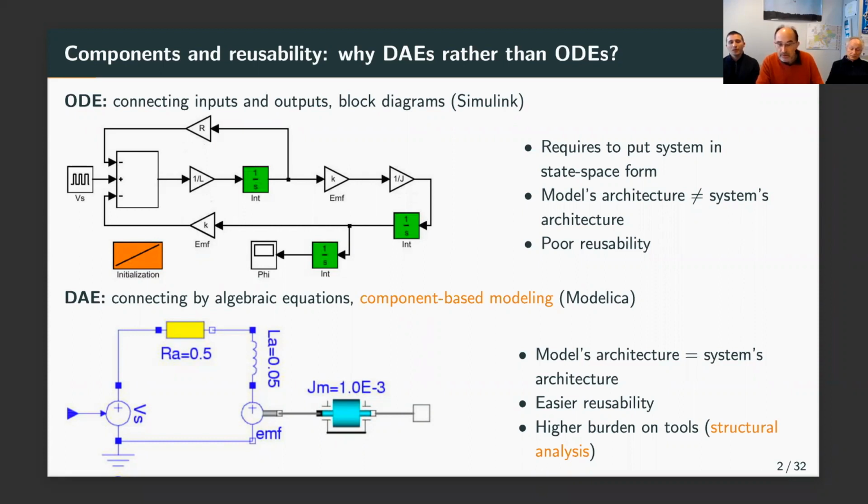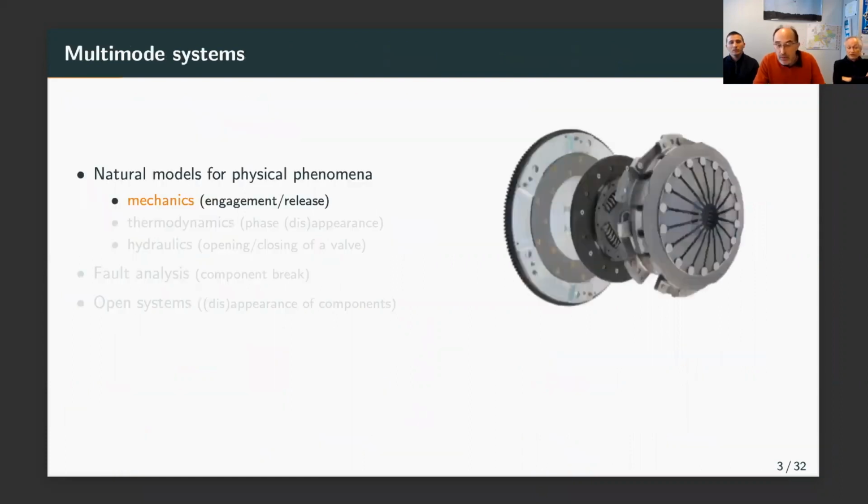And so this tells you that you will have much better reusability of the model, but this comes with a drawback: it puts a higher burden on the tools, and in particular, Modelica tools have to perform at compile time a structural analysis of the DAE in order to generate efficient simulation code.